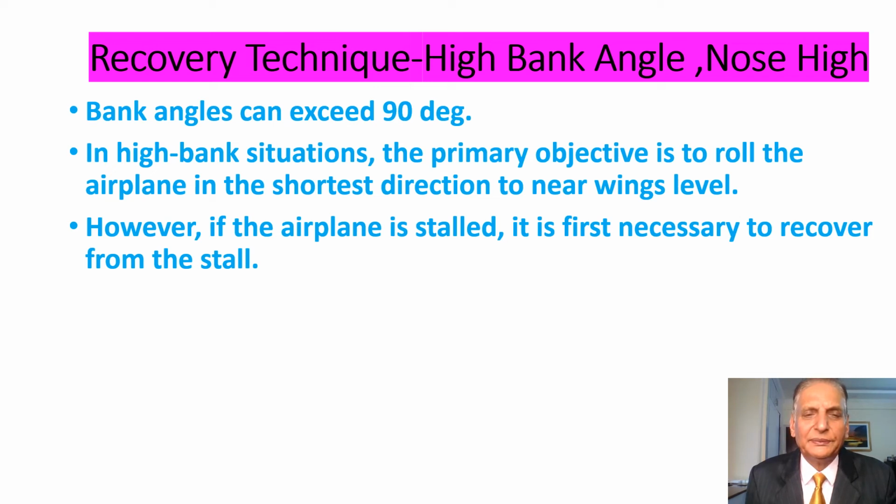Now we shall discuss recovery technique: high bank angle and nose high. Bank angles can exceed 90 degrees. In high bank situations, the primary objective is to roll the airplane in the shortest direction to near wings level. However, if the airplane is stalled, it is first necessary to recover from the stall.